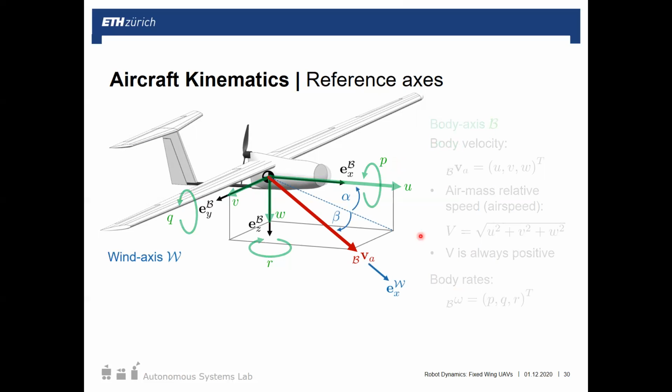So then maybe some new stuff. This is where fixed wings are a bit different from other flying platforms. So we have another axis. Again, this is an aerospace convention. It's called the wind axis. So this we rotate through the angle of attack and then over on the side slip. So I mentioned we'd clarify side slip. Side slip means we have incoming airflow on some side of the aircraft. So this would, in principle, generate some kind of side force also on the aircraft along the y-axis.